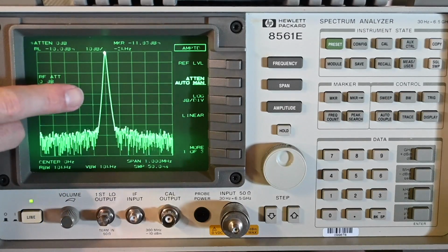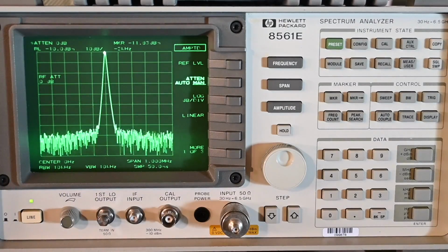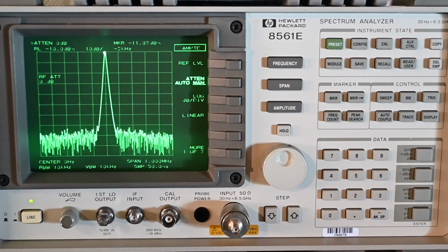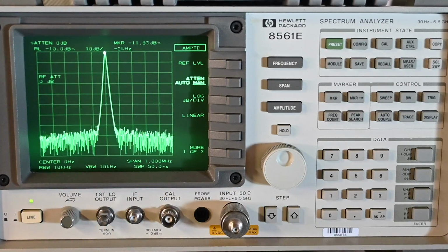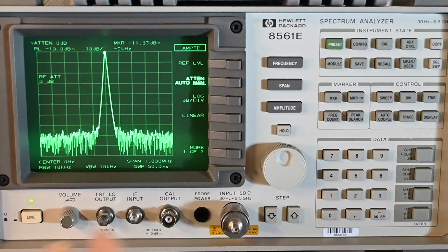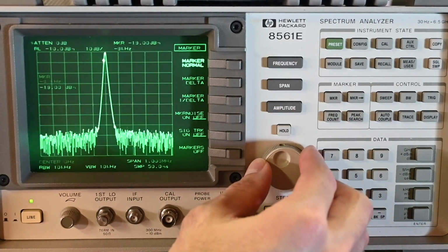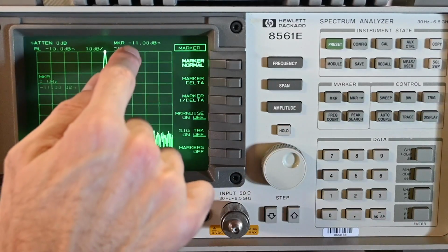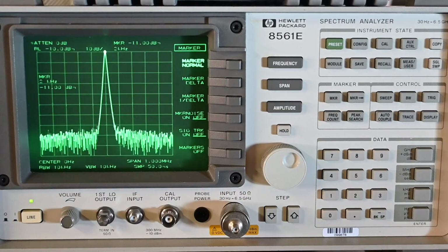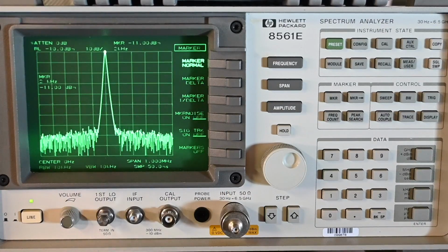So now what we're actually seeing here is the local oscillator. All right, so that's the feed through from the local oscillator. And what they're telling you is that if the local oscillator feed through amplitude is within spec, so let me look here real quick on what they're saying. Minus 6 to minus 30 dBm. Okay, so if we take a look at the marker right here, see how the marker is moving up and over that peak right there. So that marker is sitting right at minus 11 dBm. So that's within spec, because they're saying from minus 6 to minus 30 dBm.